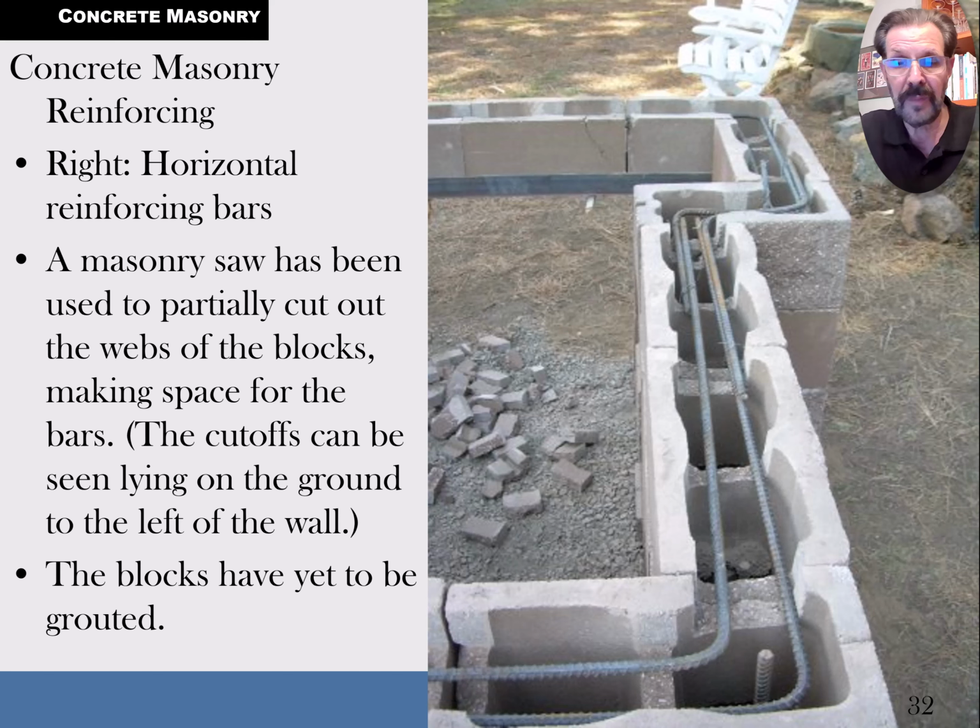But here we go. This is showing you one way to do it, and that is, so these horizontal beams that are hidden inside, we fill and pour concrete there with the horizontal steel. We're making a beam hidden in the wall. Now this is a little unusual. We got a bond beam down at the bottom. It's right near the bottom. Generally, the first bond beam in a wall is usually about 8 feet up, maybe over top of the windows and doors. If you've got windows and doors in the wall, about every 8 feet up a wall, and up at the very top of the wall, you will always have a bond beam.